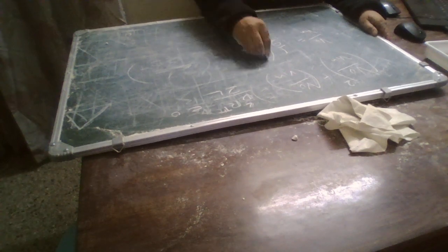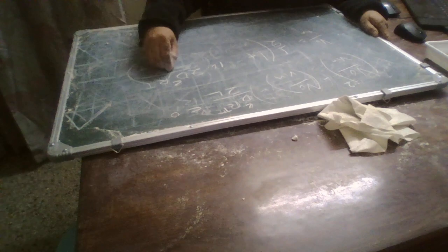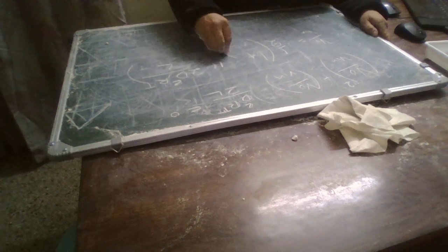We can solve the quadratic equation, and after solving it, we will find that V output upon V input equals half of 1 plus the square root of 1 plus 2 d square RT upon L, and this would be the discriminant.